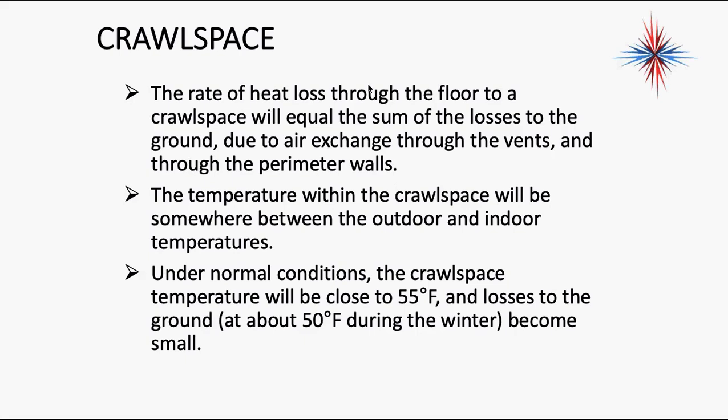Under normal conditions, the crawl space is close to 55 degrees, and the losses to the ground, which is about 50 degrees in winter, become very small. But then again, you have the loss from the house that you're trying to maintain at 70 degrees to the crawl space. So again, there's heat loss all the way through. Crawl spaces are not all that great.